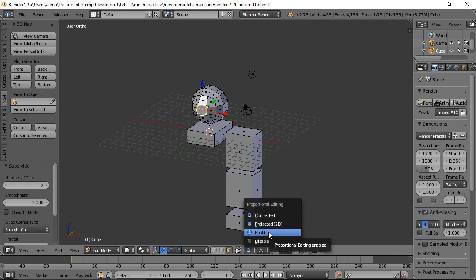The one version of proportional editing, which is here, allows you to manipulate vertices, edges, as well as faces wherever your area of influence for your proportional editing tool falls. We pressed Alt-O because O turned on proportional editing. That's one of the shortcuts for it, besides just going here to this menu.